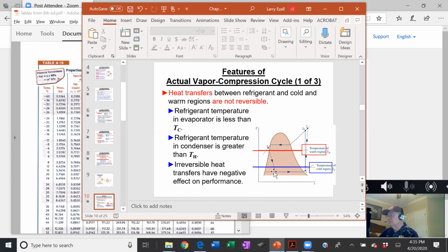Well, maybe not. It depends on the statement of the problem. This position going into the compressor shows it slightly out in the superheated range. Normally, it would be right on this line as saturated vapor. In other words, we go to the tables at this pressure or temperature and get Hg. Then the compression process, like before, is adiabatic and isentropic, S1 equals S2, constant entropy.